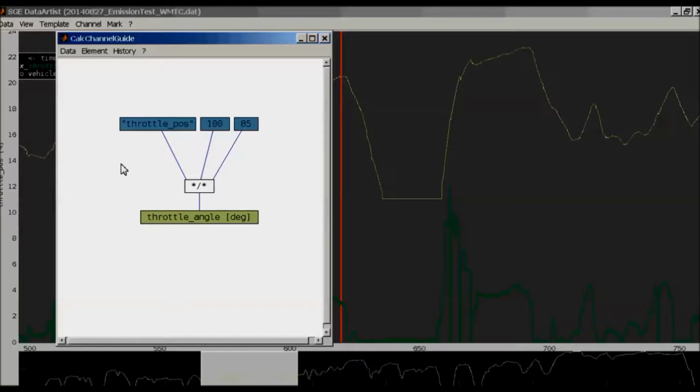To tidy the calculation a little bit, we can use line branches. These are created by double-clicking a line, and then we can avoid, for example, line crossings by creating these line branches. Some color indicators help us to detect errors in the calculation. So for example, if I delete this line, we will see that the two unconnected blocks are marked with a red border.